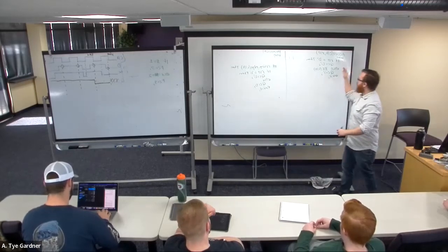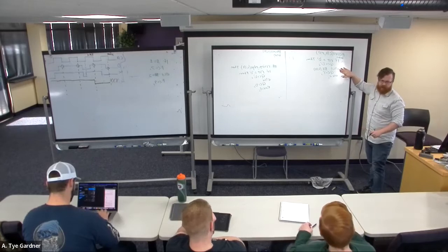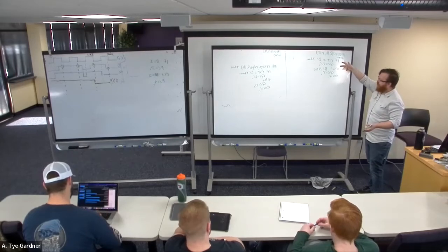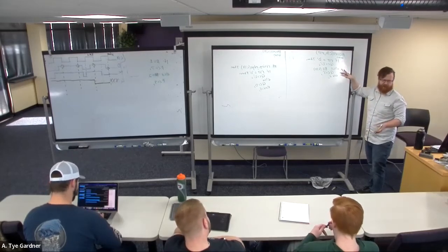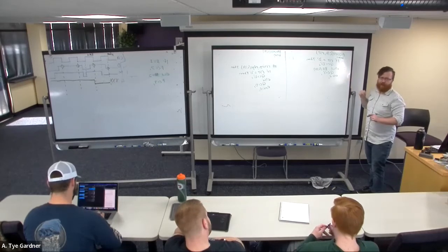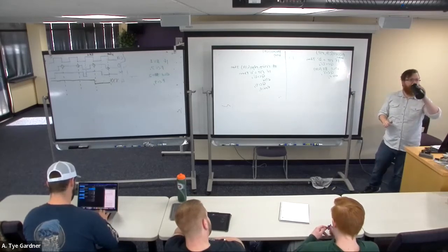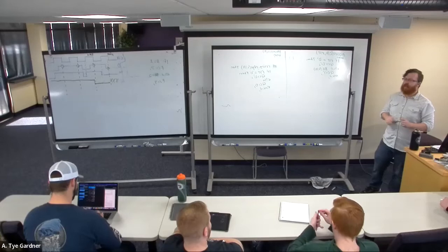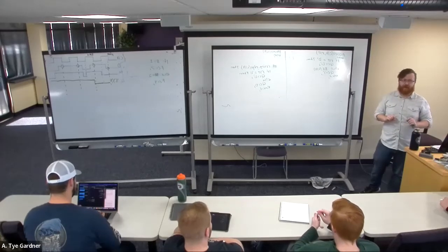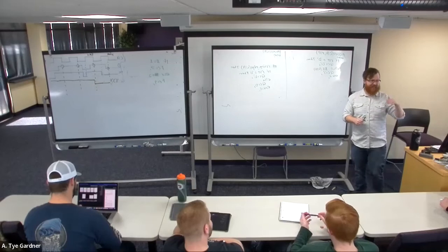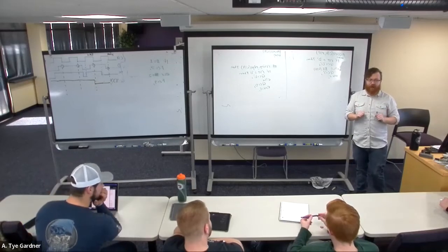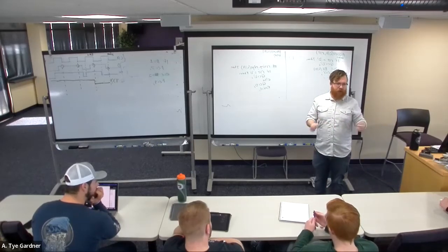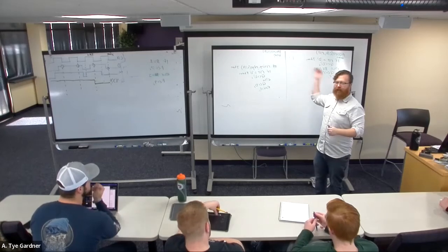This is saying that if the reset is true, we don't care what the rising edge of the clock is doing, which is what we want, right? We just want it to be 0. If they're flipped, then it's saying if the rising edge of clock is happening, I don't care what the reset is doing, which is not what we want. So this is one of the few times that order is important in VHDL. Yes, order is important in sequential logic, right? Because it happens in order. It's this, then this, then this. That's the idea of sequential logic, is suddenly order matters. In combinational, it didn't, right? When we're doing combinational, it only depended on the combination of the inputs. Order of your expressions didn't matter. Now it does.